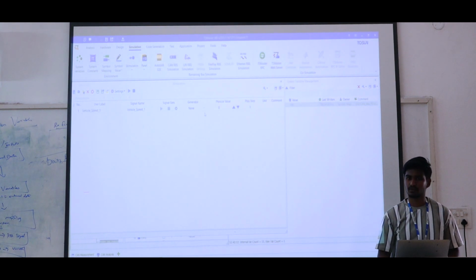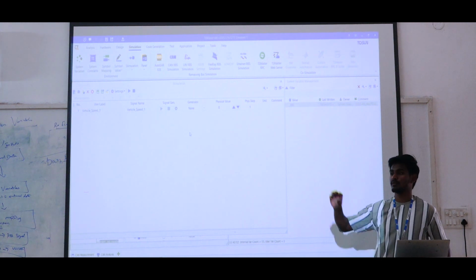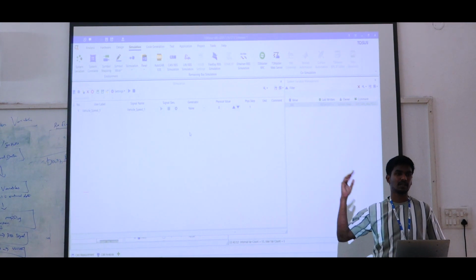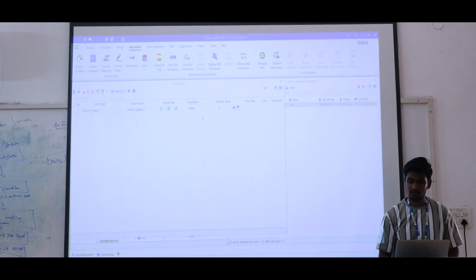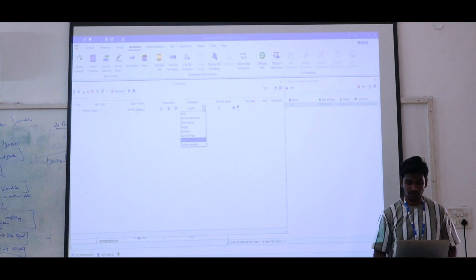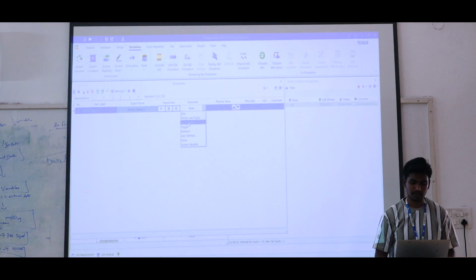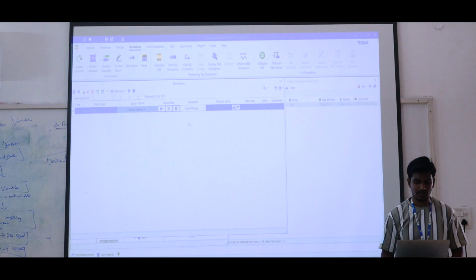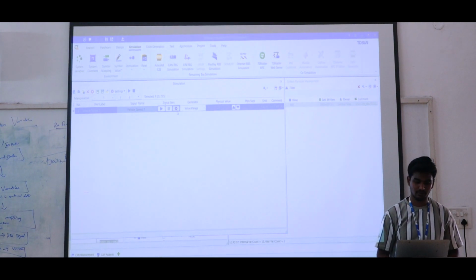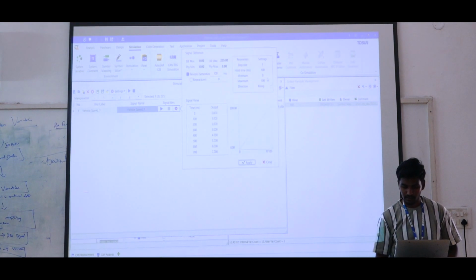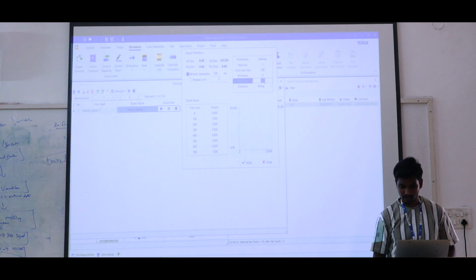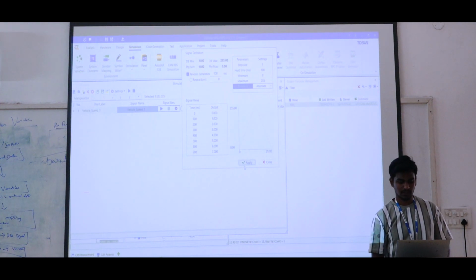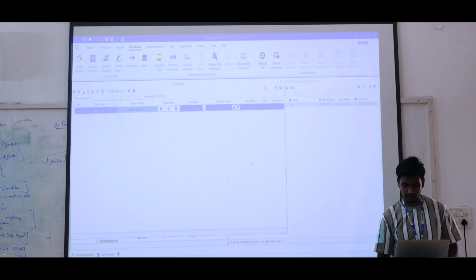So here also now it is showing the same signal generator block what we have seen in our transmit window of IG block. So here you are having generated IG block there. You can give like a value range, ramp, impulse, random, whatever we have. I can explain the value range. So we can use the value range, the same settings you have to follow. The settings are here the value is maximum 255. So you have to mention 255 and then take it as alternate. So then give apply and then close.